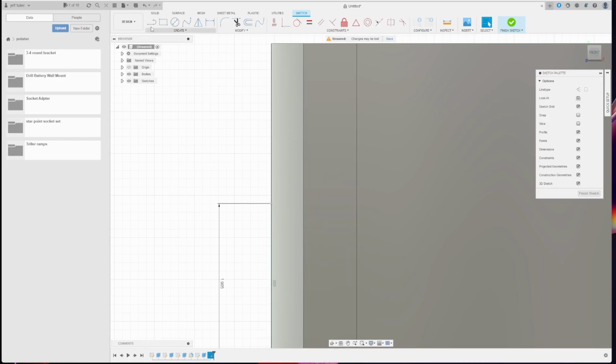We're just going to hit escape again and try this again. Select the point, we'll drag a line, we'll say 0.08, which is 80 thousandths. We'll divide that by 2. Then we're going to tell it we want to be in inches, and it can't do all that math. That's fine. What we can do is set our line. We can say 0.08, and then we'll say IN.